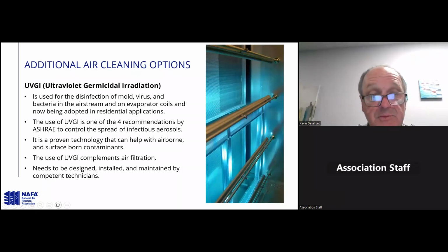UVGI, ultraviolet germicidal irradiation, is a great complement to mechanical air filtration and can be used in conjunction with it. In a lot of cases it's put into the duct or right into a room. So again, a very good option if you're worried about irradiating live virus, bacteria, mold, that type of thing.